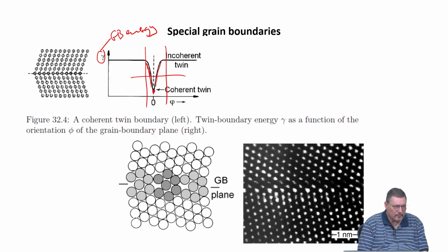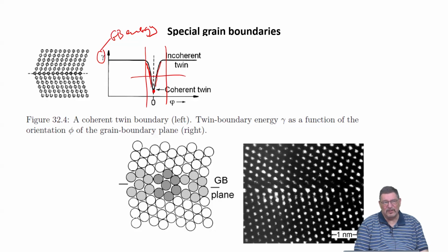So from the tip of the twin, we can identify if it's a deformation twin or not? This is very difficult. Yeah, you can look at it in terms of shape. If it is very straight over a long distance, and you do not see many dislocations associated with it, like strain fields, I mean, you can look at the kernel misorientation maps associated with the boundaries, and if this is rather a uniform color, that means that there is no strain variation along the boundary, and then it is a good indication that this might be a grown-in twin. For a deformation-induced twin, you would think more variations, or you get maybe steps in it or something like that.